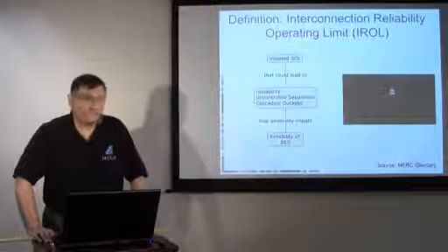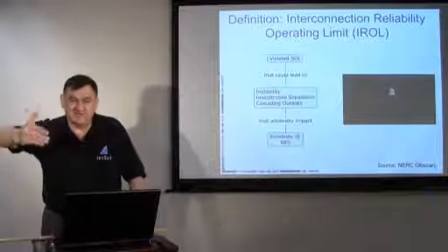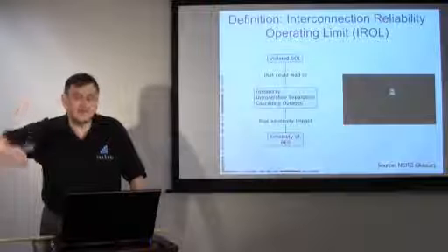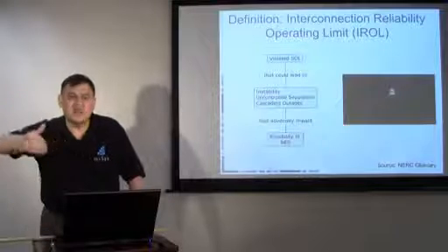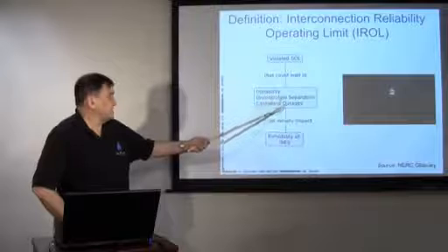your reliability coordinator. And like we saw in the September outage in Arizona and California, any one of the system operators at different levels could have actually run some studies that said when that Gila to Hassayampa line goes out of service, we have an instability and a cascading outage.